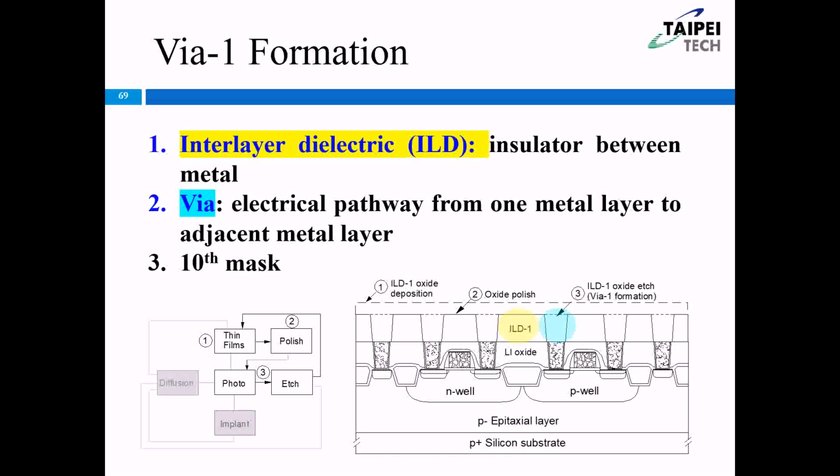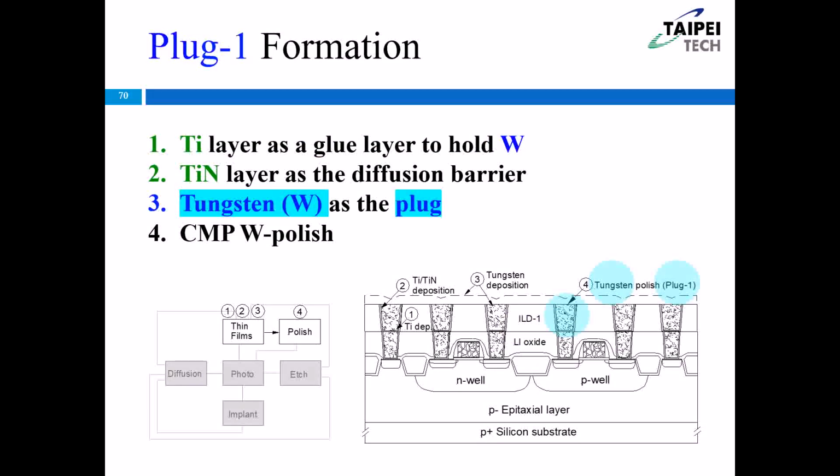后面的制程都一模一样，它的制程全部都一样. So right now we can define the oxide pattern. We define the oxide pattern just like the processing tool here. We etch the silicon dioxide, OK? And then the next one we need to put the metal. Here is the tungsten. We put the tungsten into the gap between the oxide. So right now we still need to use the tungsten plug. Where is the tungsten plug? Here. We call it the tungsten plug. The blue region is the tungsten plug.